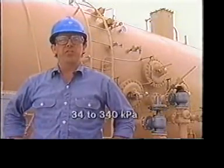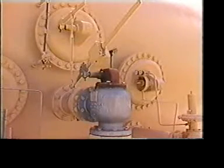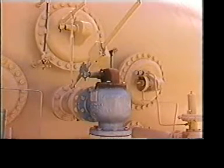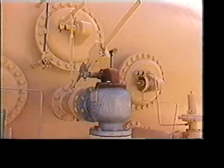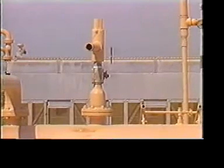Most electrostatic treaters operate under working pressures of 5 to 50 psi. The maximum working pressure for any treater can be found on the manufacturer's information plate attached to the treater. Oil, water, and gas discharge lines must be equipped with controls, and the treater itself should be equipped with pressure relief devices that have enough capacity to protect the treater if pressure increases.